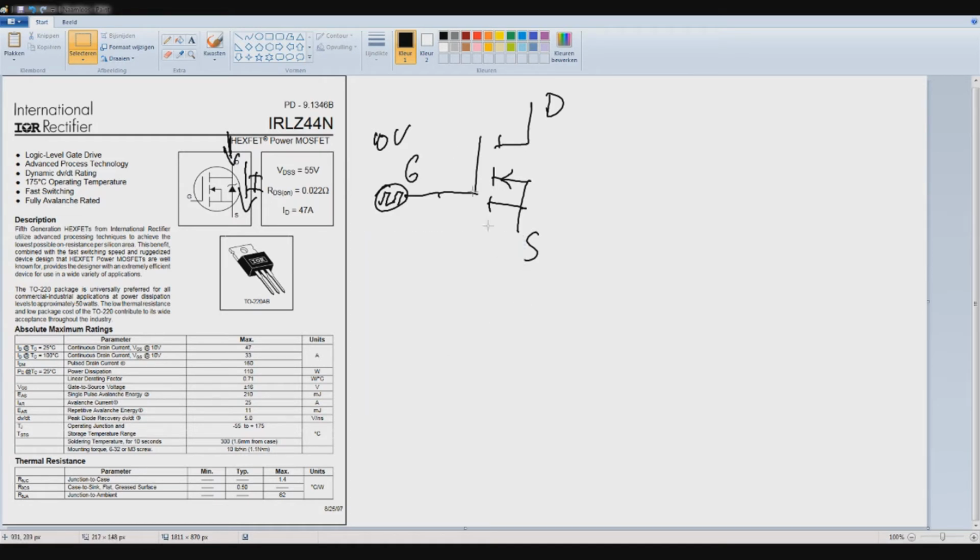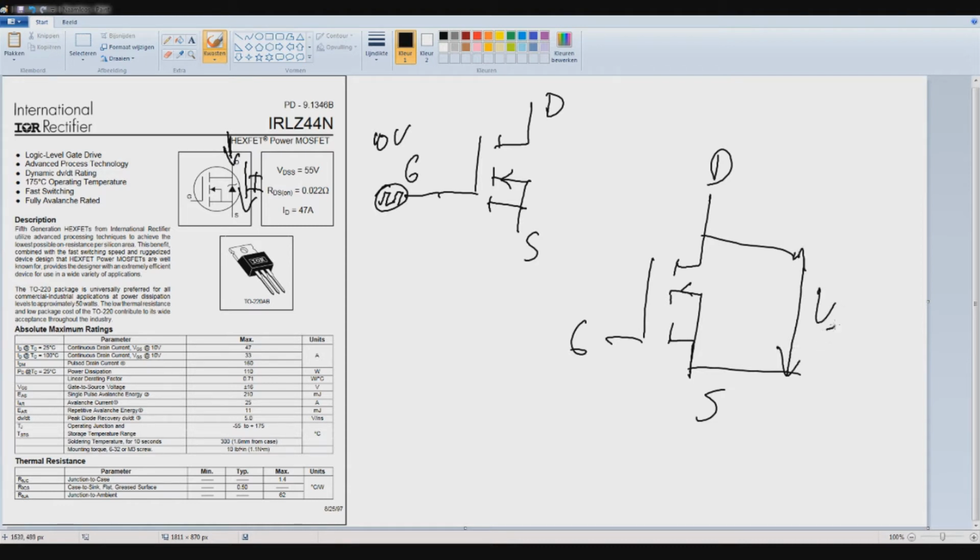Therefore what it means is, for example, we have a current flowing in our circuit, and the voltage drop across this is a certain voltage, and the current through here has a certain value, and therefore the power dissipation is this current times that voltage drop, and apparently that shouldn't be higher than 110 watts, because then it will cause troubles.